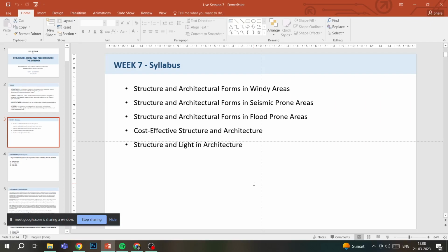A lot of these aspects were discussed and covered. And then different earthquake resistance techniques were discussed, like shear wall, like bracing, and horizontal bands, and other aspects. And then it was discussed what is bracing, different kinds of bracing, and all those points were covered.